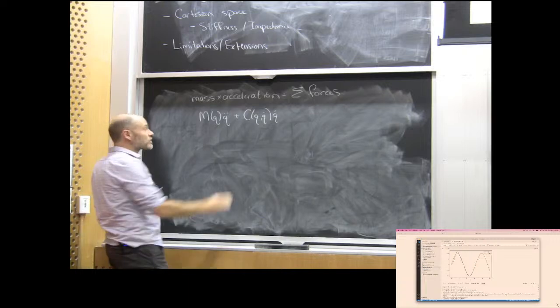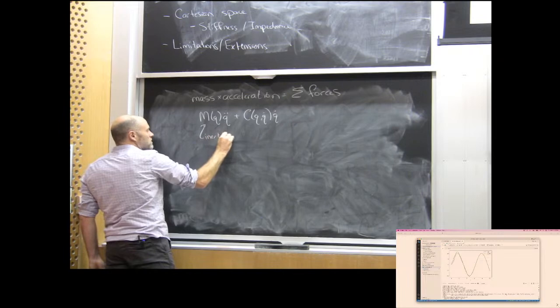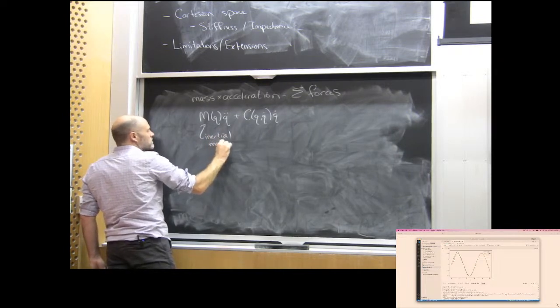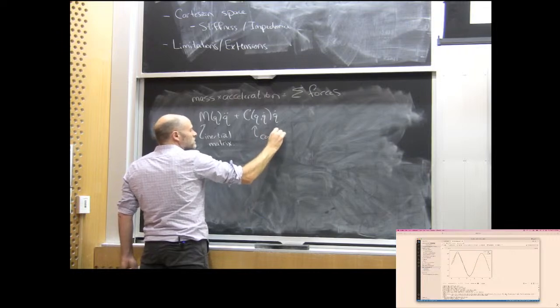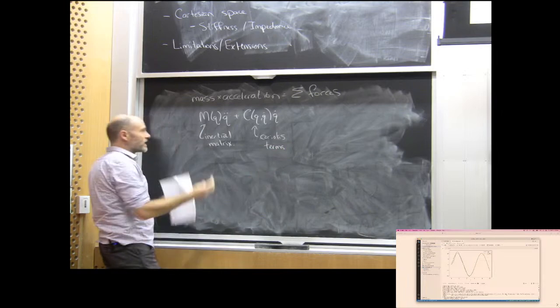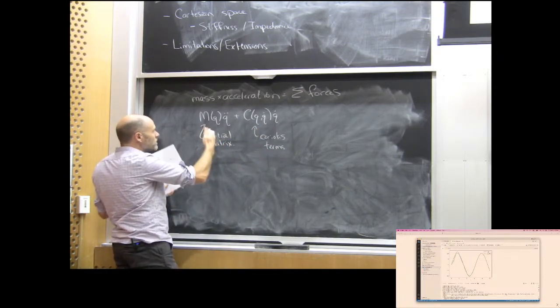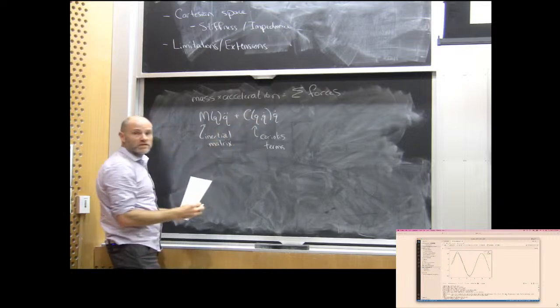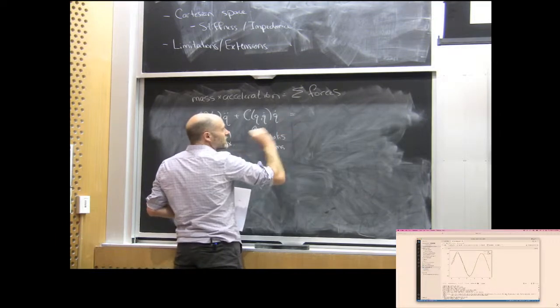This is now the inertial matrix. These are the Coriolis terms, but they really go together. This is M. You should think of this together as MA. If you were to change the coordinate system, then they would both change equivalently. This is MA. Okay, and then we get the sum of the forces.